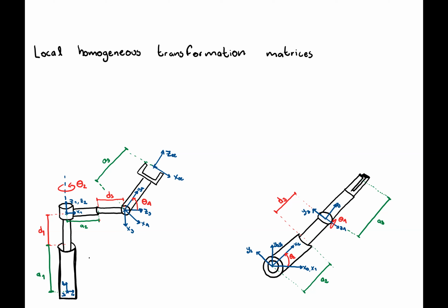We already went through the first prismatic joint, the second rotational joint, and then we did the third, the second prismatic joint. Now we want to do the transformation to this rotational joint here. Remember that the Z axis is always aligned with the axis of motion of the joint.